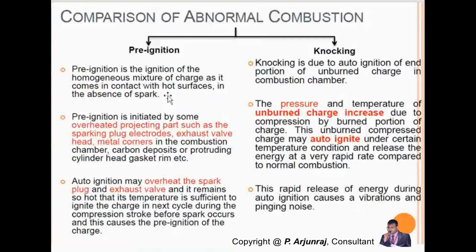that is not pre-ignition, because pre-ignition does not happen with the help of the spark plug. The spark plug is there already, but it will not produce any electric spark or any heat during that stage. But because of the high temperature already present in the spark plug electrode or the exhaust valve head, that temperature itself is sufficient for the combustion to take place. It means that instead of going for the ignition stage, it goes for a pre-ignition stage, where it goes abnormal.